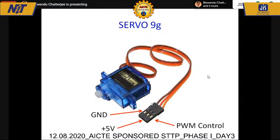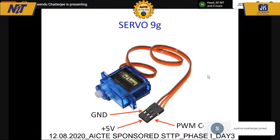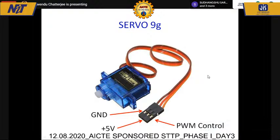And for electrical connection, there are 3 pins. The brown color pin is the ground. Almost all servos follow this convention. The middle one, the red one, is the positive, and the orange one, on the right side, as you can see, is the control terminal of the servo. With the help of this terminal, you send the control signal to the servo so that the servo can turn to a desired angle. This is the PWM control.